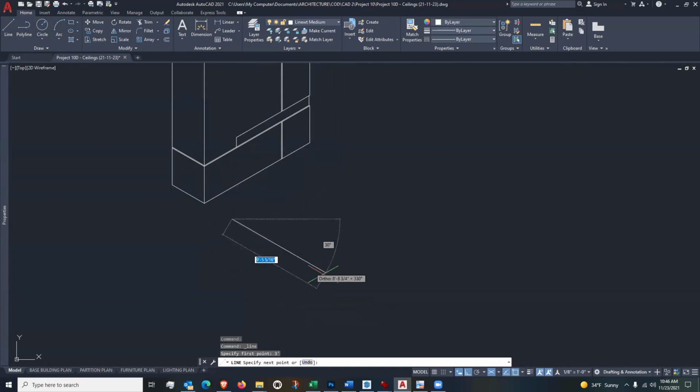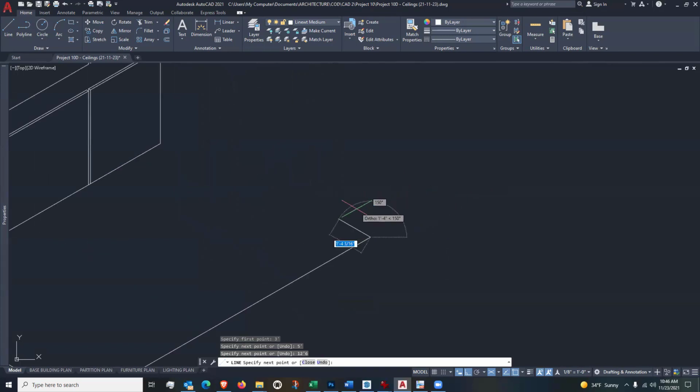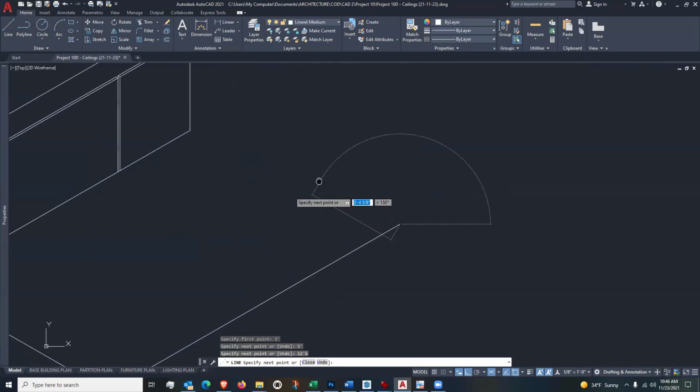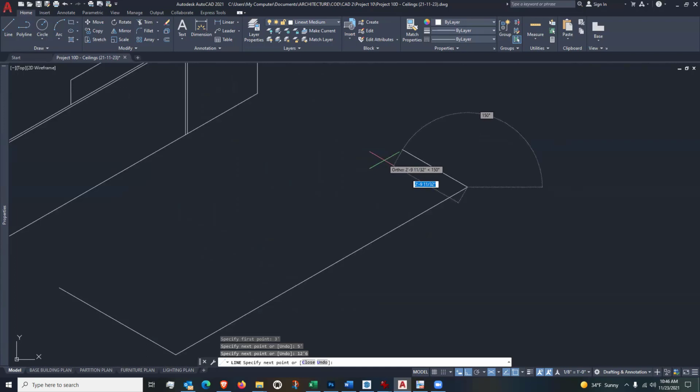And the overall depth of the reception desk here is 5 feet. And that curve is there. And we'll talk about the curve later on. So I'm going 5 feet out. And then the overall length is 12.5 feet. So 12'6". And then it comes back in this direction. And this is where the accessible piece of counter is. It comes back 3 feet.